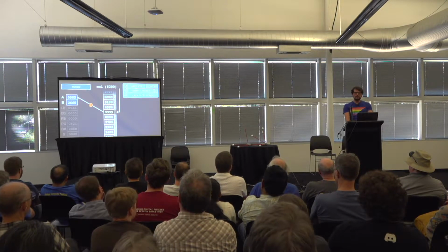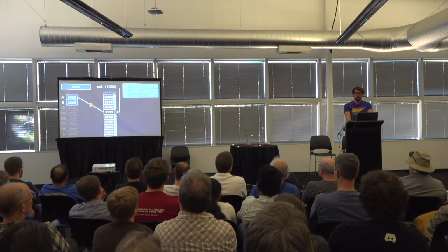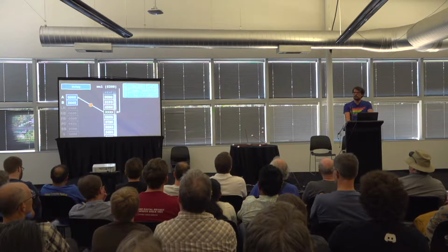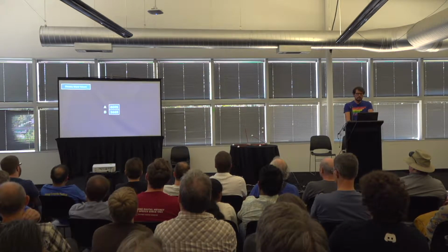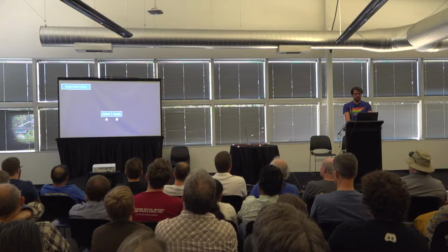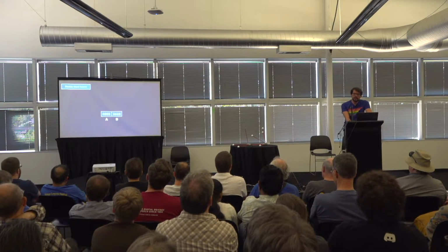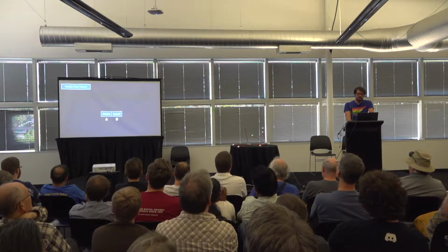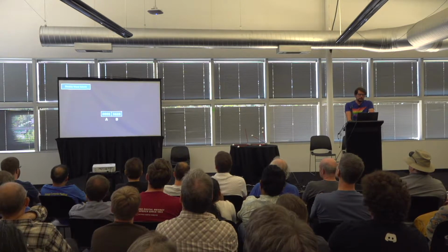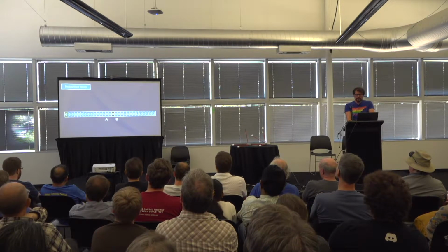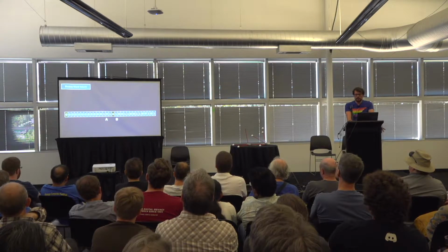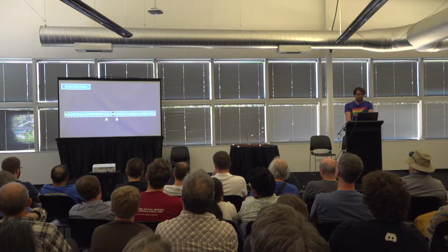B is a separate 15-bit register, which is mostly used together with the accumulator with instructions that deal with 30-bit data. Double word values are expressed with the uppermost bits in A, or if in memory, at lower addresses, and the lower bits in B or at higher addresses, making the AGC a big endian machine. Assuming the normalized form with matching signs, the effective value is the concatenation of the 2 times 15 bits of the values.